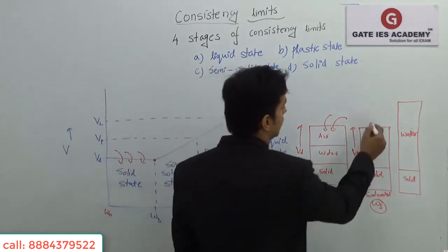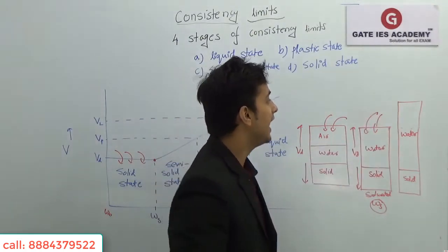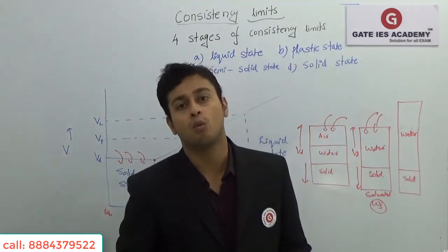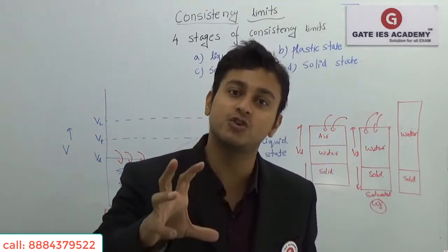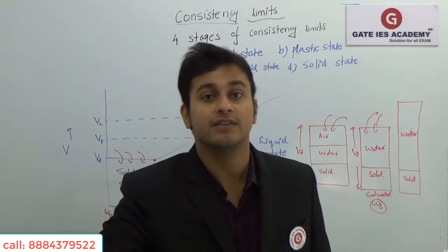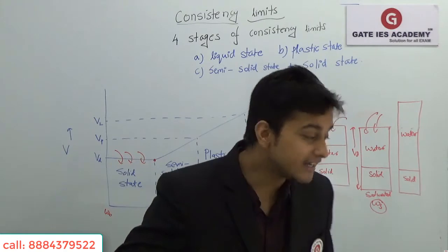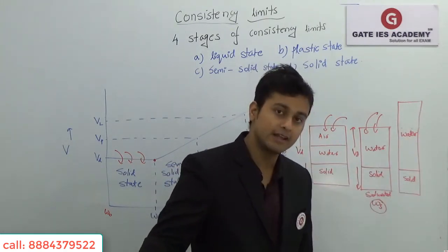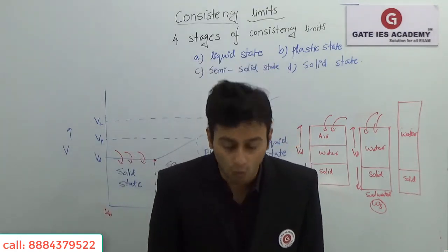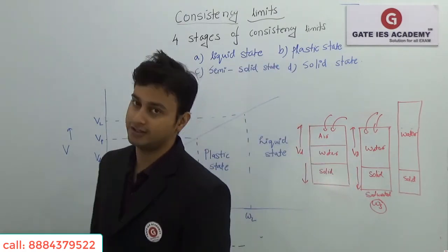Now what happens if I add water? Obviously the system volume will start increasing and will keep on increasing as you add water. So the void ratio will also change, because the net void volume is changing. Your whole system will be in the saturated state, but the volume of the whole system, the voids, the porosity, the void ratio, everything is going to change.